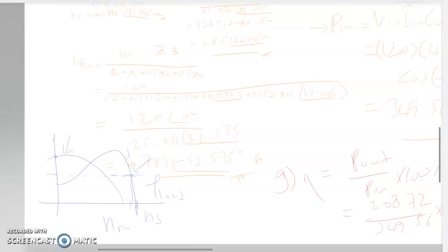Unless your load profile is like this, where at a certain speed, when the speed increases, the load also increases. So you can use this one, because at the starting point, the torque is already higher compared to the load requirement. Or let's say the torque profile is like this, meaning the starting torque is already higher than the starting requirement of your load. So you can still use the running coil instead of putting in another auxiliary coil to provide the higher torque to the system.